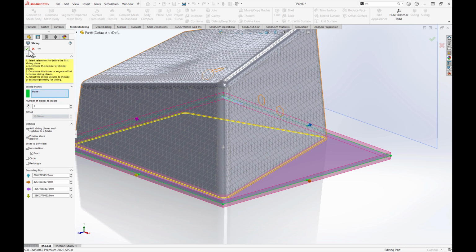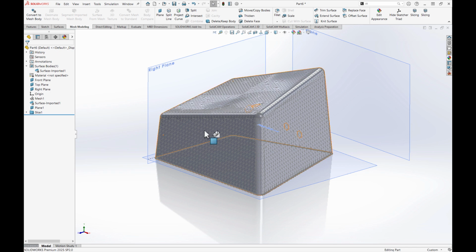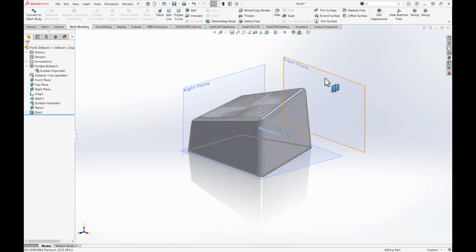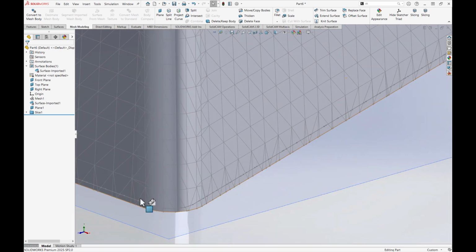Now, granted, there'll be a slight discrepancy there because this plane is a very small amount above the top plane, but I'm willing to forego that accuracy. I think I'm down at the 2nd decimal place in terms of millimeters, so that discrepancy is minimal at most. So then what I do is I probably create some other planes, so you could do some offsets from either the right plane or the front plane, and then I could create some more slices using those as well. And I could work from these slice shapes when I create my sketches.